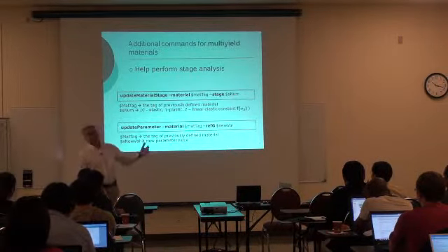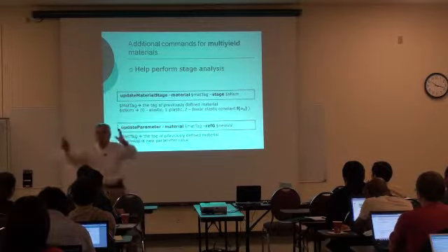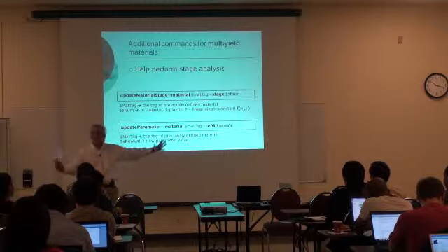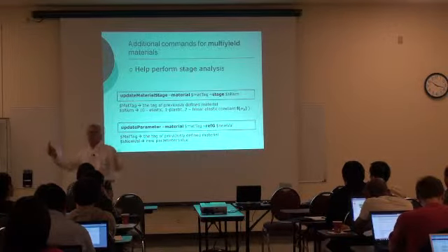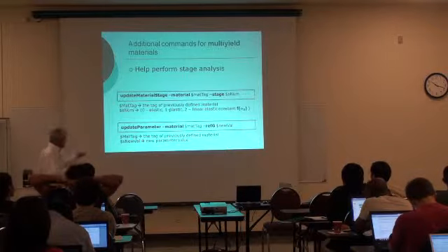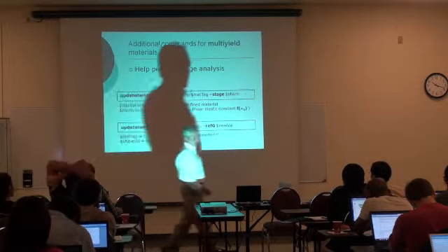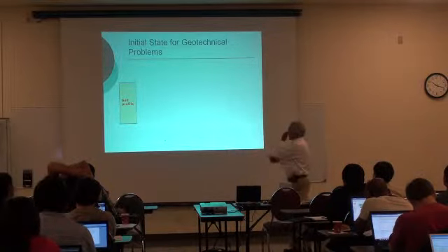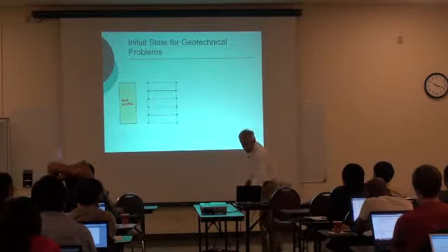So that type of analysis can be done, for example, by updating your parameters. Or you may assume that the initial state is normal, and then you say, well, let's assume that the soil liquefied. How do I do that? Well, change the parameters to those that correspond to a liquefied situation in some layer. You can do that using update parameter. So it's very useful.